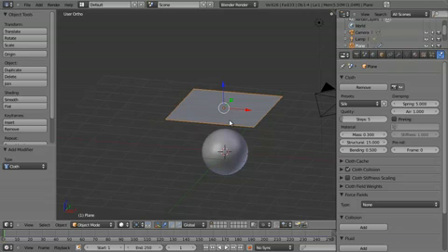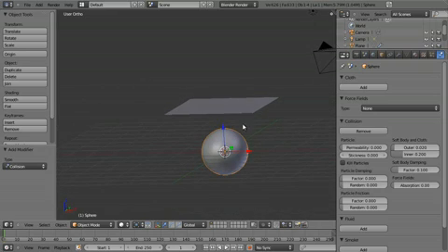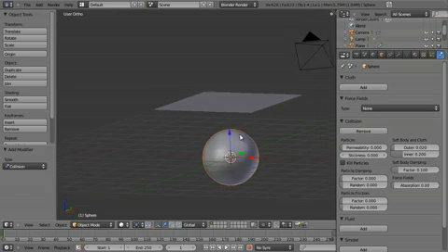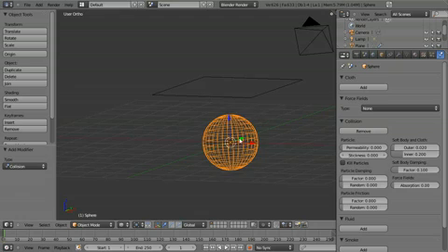And the first thing I want to do is let's go ahead and make it collide with the sphere. Now, with the physics simulations, to make objects collide, you have to define that object as a collision object. So we can just select the sphere, and then just click Add Collision. And the default settings will be fine for now. And the only ones that refer to the cloth really are these soft body and cloth settings right here. The outer determines how close to this surface a cloth object needs to get in order to deform or to collide. And then the inner is within the inside of the mesh.